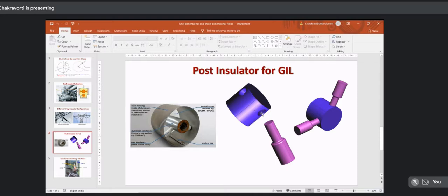There is a hole here. And this cylindrical insulator, which is white color in the left diagram, will go into the hole. In this way, we make a V-type configuration, and you can see on the left a truly V-type configuration. But once we do that, I cannot say it is rotationally symmetric or two-dimensional. So I have to go for three-dimensional field calculation.